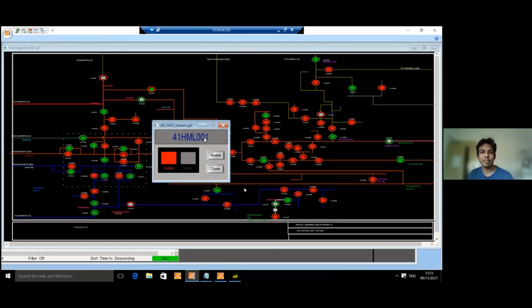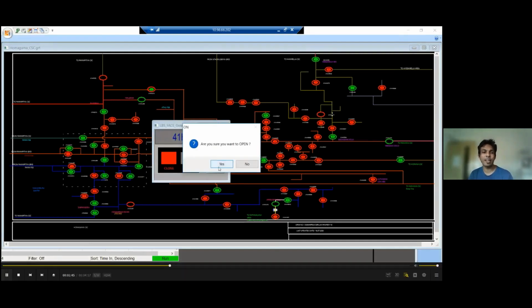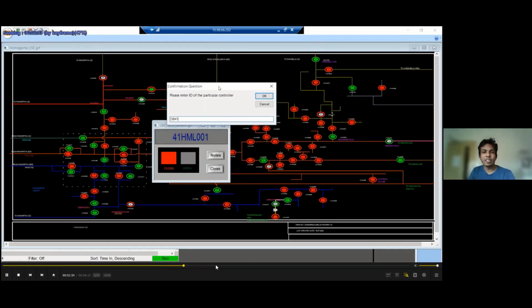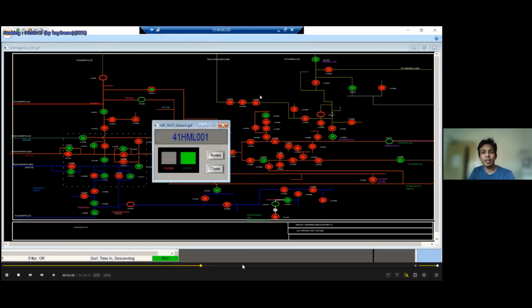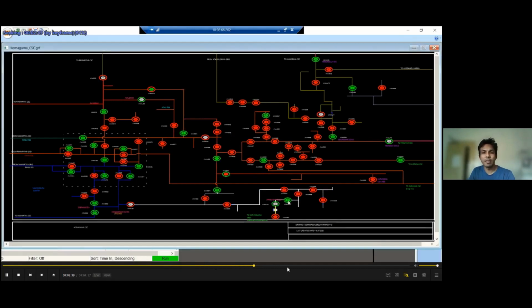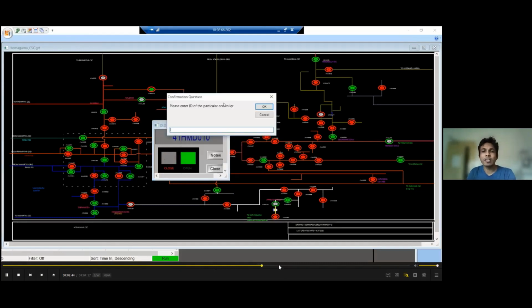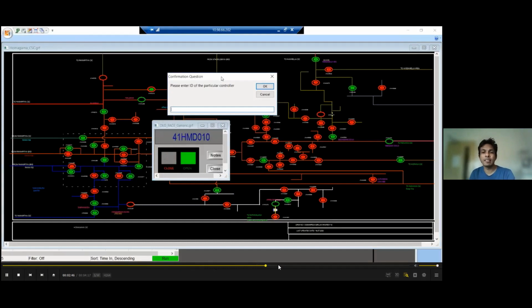Now, like Dinesh explained, we have those air brake switches which don't have remote communication capability, but we can incorporate these as well. Without the communication medium, just to have a mimic, you can have these things and show the line energization status.